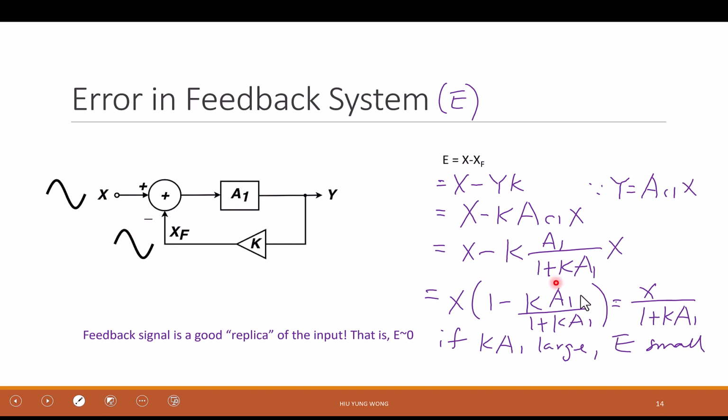This is very useful to myself when I design a feedback circuit. If it doesn't work, to trace the error, sometimes I just probe these two. If I don't see them trace each other, I know my feedback circuit is not working. If they trace each other, then maybe it is working, but I just have the wrong parameter.